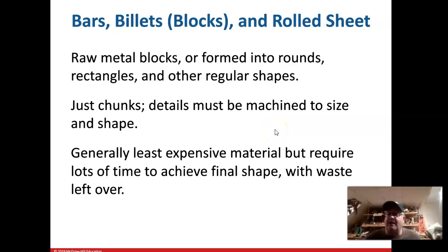And of course, generally, that is done by your fractional sizes on the imperial system. Or you may also be able to buy it in basic metric sizes as well, although here in the States, most of the time it's imperial fractional sizes. Sometimes there's some allowance and clearance depending on whether it's hot rolled steel or cold rolled steel. But for the most part, it's going to be pretty close to the actual size, fractional sizes, an inch based measuring system.